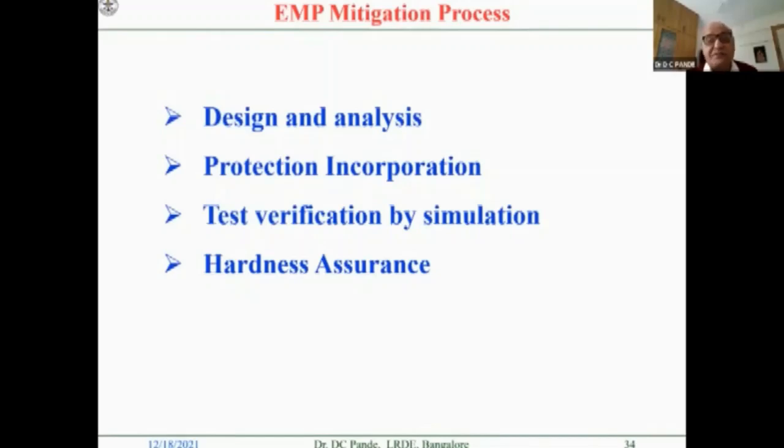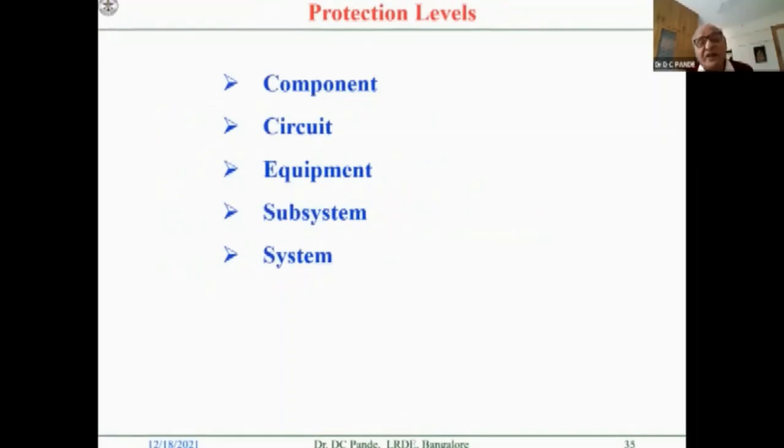Once the protection has been done on that particular facility, the EMP is to be simulated, and the facility tested in the simulated environment to see whether it complies with the requirements. Then comes the hardness assurance testing. When we do the protection, it starts from the design. You can't retrofit this type of protection.